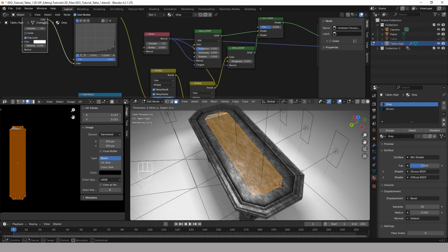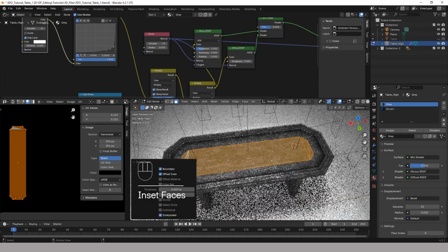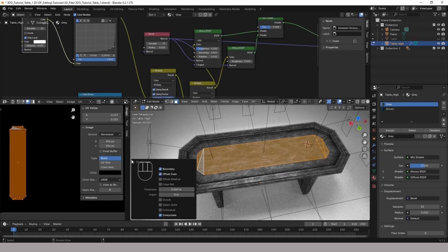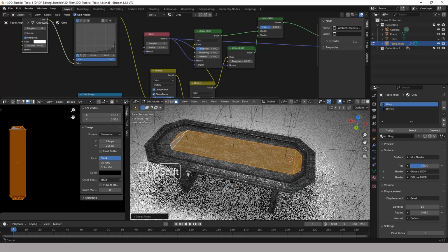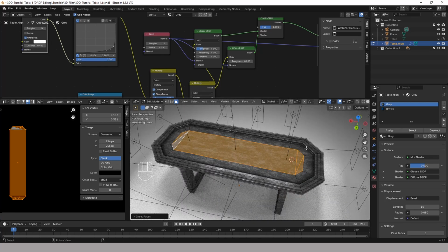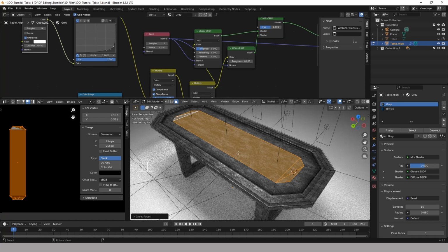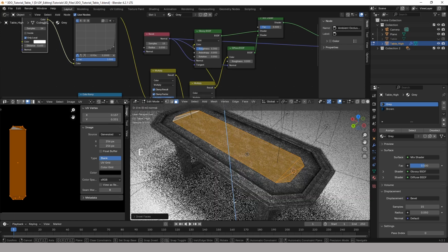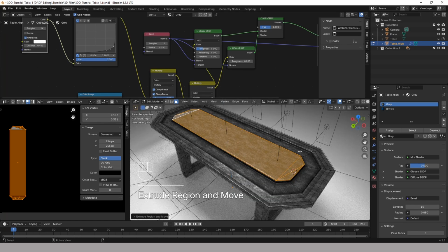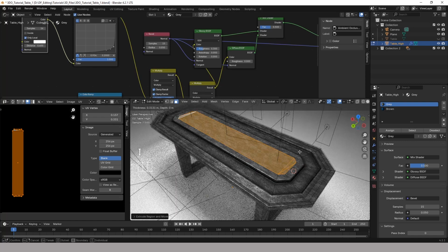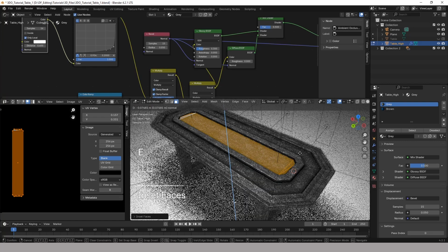So you can imagine already what that sort of thing is useful for. If you've got girders and you wanted to cut uniform holes in the girders, or just any sort of shape that looks like it was mechanically done on purpose. Some organic uses for that as well, but these edges will now be of a uniform length. And so it gives that look as if it was designed to be this way on purpose, which is what we're going for. So if we were to E extrude in the middle here, I to inset, E to extrude to just bring that down a bit.